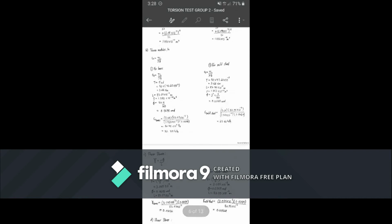For the calculation, we just insert the values into the formula. So next we will get the answer. This is 32.44 gigapascal. For the mild steel, we also use the same formula, G equals TL over J times the angle of twist.